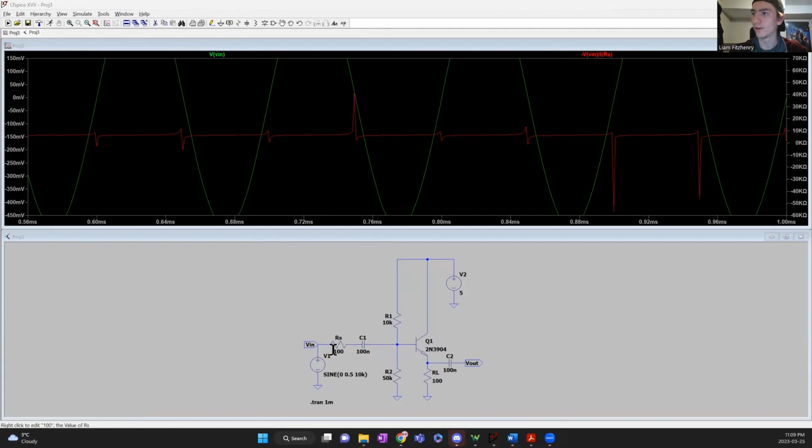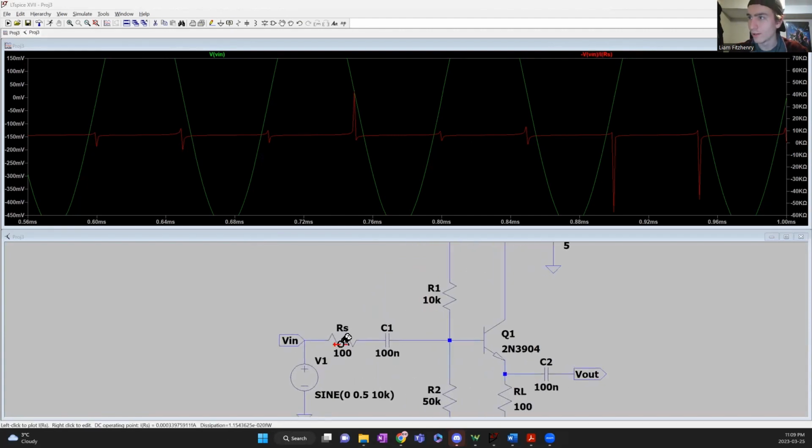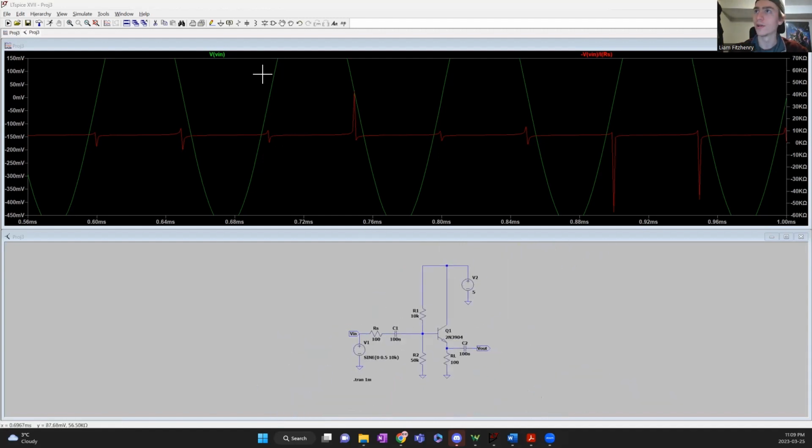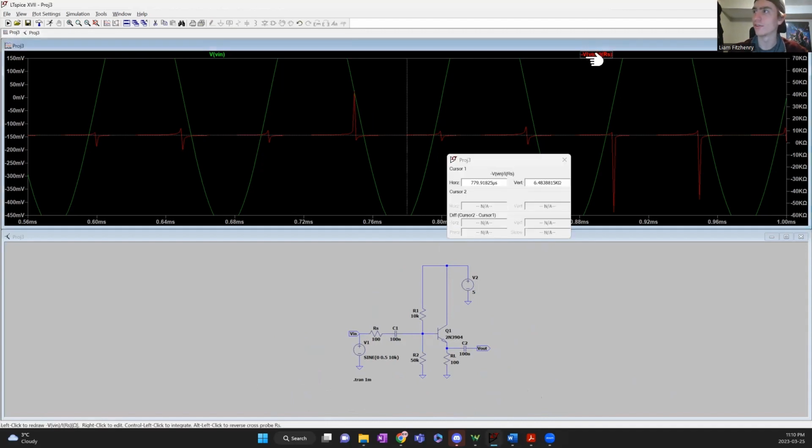You can see this negative sign here because LTspice by default has current going left, or at least it does in this case. I don't know how to change that, so I just threw a negative there so that it would be the current going this way. So input voltage divided by input current. Again, we're going to have some weird spikes here when the current crosses 0 in particular. So what we're really interested in is the average value in the linear region of